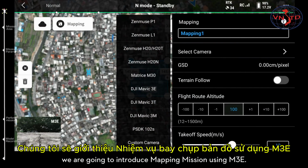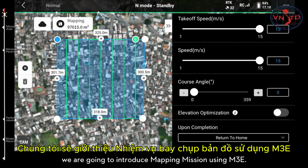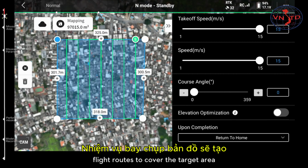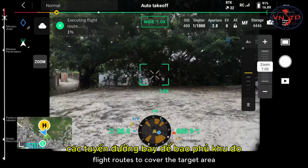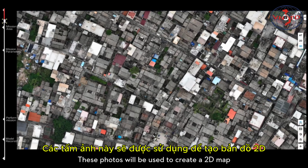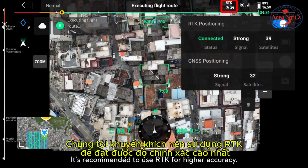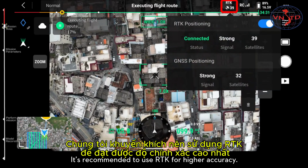In this video, we are going to introduce Mapping Mission using M3E. Mapping Mission will create flight routes to cover the target area and capture photos during flight. These photos will be used to create a 2D map or 3D model. It's recommended to use RTK for higher accuracy.